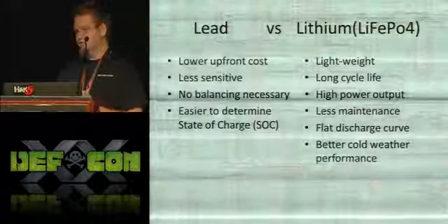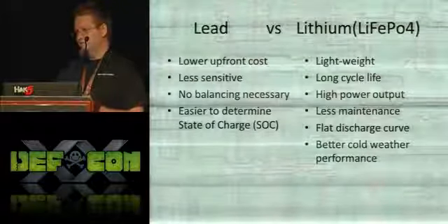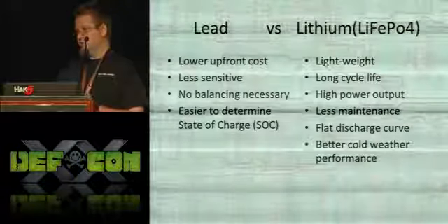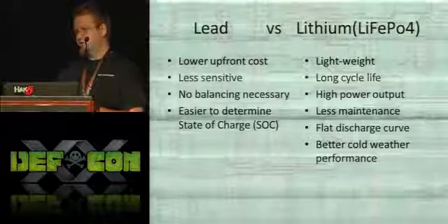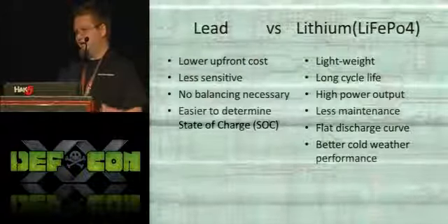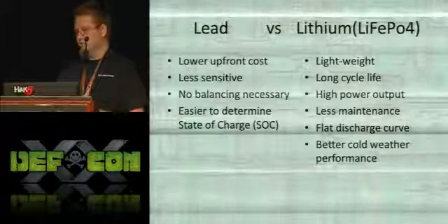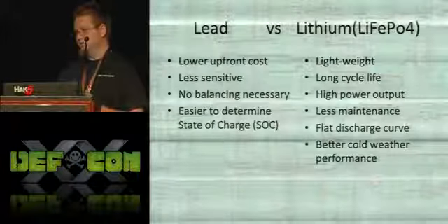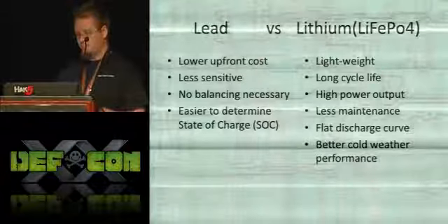They're less sensitive because a flooded lead battery, you can't overcharge. All it does is turn into a fuel cell once it's full. So it just gases, and all you have to do is add water to it, and it's okay. Whereas a lithium battery, if you overcharge it, you'll vent it, which destroys the battery.